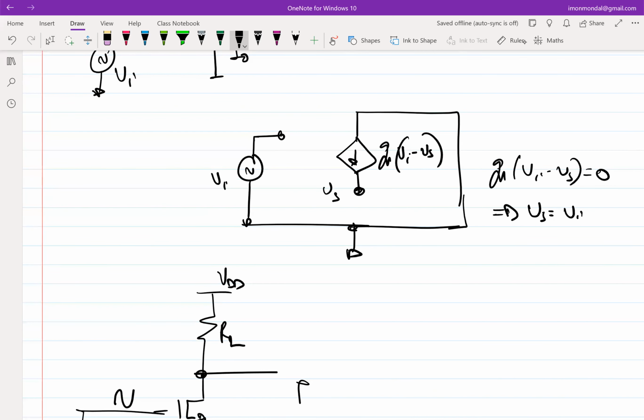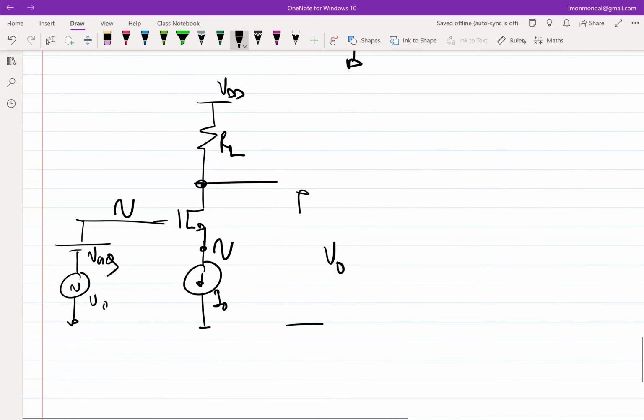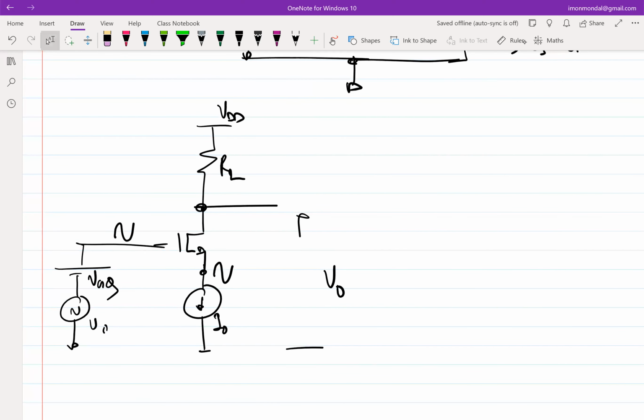If the gate voltage increases, the transistor is trying to push in more current, but it cannot, because it is biased with a constant current source. So the only way it can reconcile this problem is if it pushes the source along with the gate, right? If the source swings along with the gate, the difference between the gate and the source doesn't change, which means everything is satisfied.